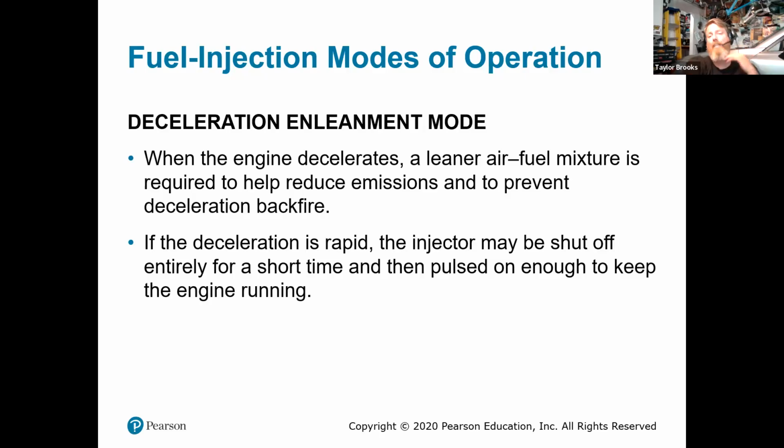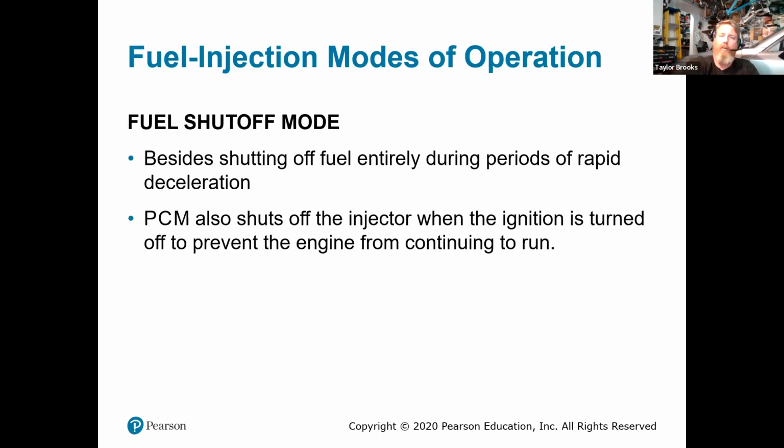The very last stage is going to be the anti-dieseling mode. Dieseling is where there is enough manifold pressure that it can force the needle and pintle open on the fuel injector, basically overcoming the return spring pressure, and it will cause the engine to still run. Now it runs rough, and can backfire and potentially be very damaging to the engine. But that is the last thing we're going to have in our injector modes, and that basically is going to allow it to shut off entirely.